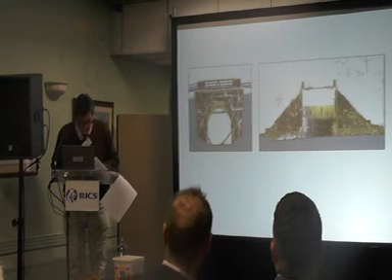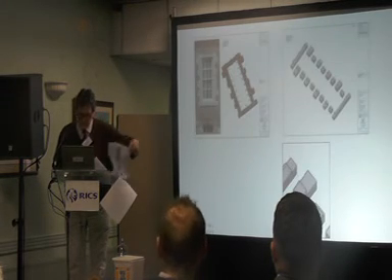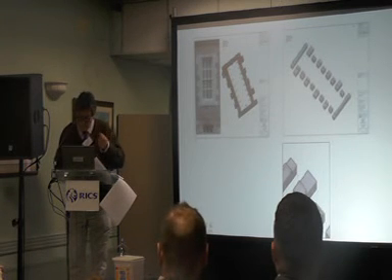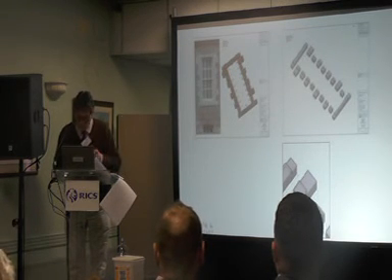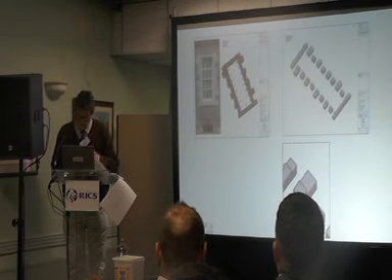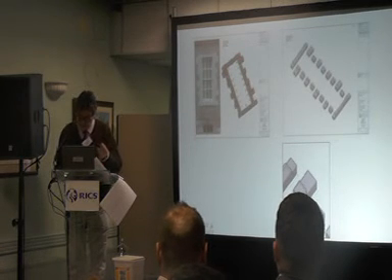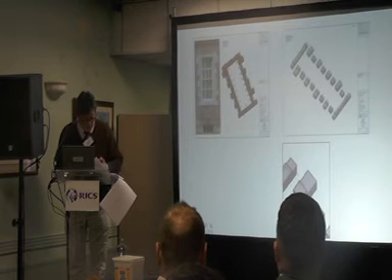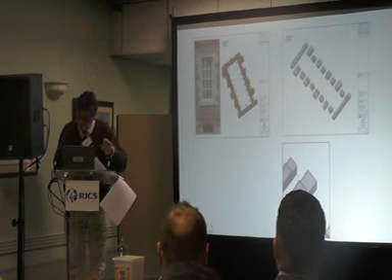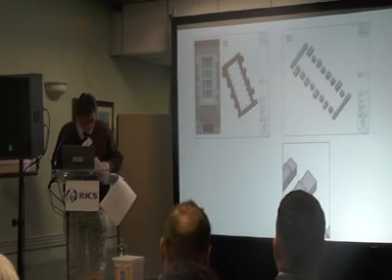Now, what we do with that, we use a digital jelly mould. We convert the drawings to 3D on CAD, and then we create an STL file for each stone we need. Now, an STL file is a 3D file which drives a computer-aided CNC cutter. So one of these marvelous new cutting machines is computer-driven rather than human-driven.